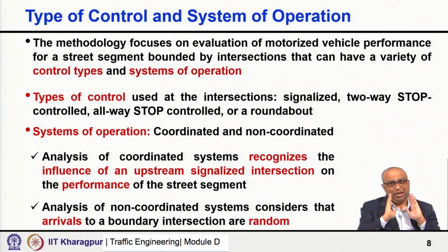So, the major traffic is traveling in a particular direction at a given time, typically in the morning peak towards the city or CBD area. Therefore, when signals operate in an isolated or non-coordinated manner, you will leave one intersection, you can see the downstream intersection is green, but by the time you reach there, the signal turns from green to red.